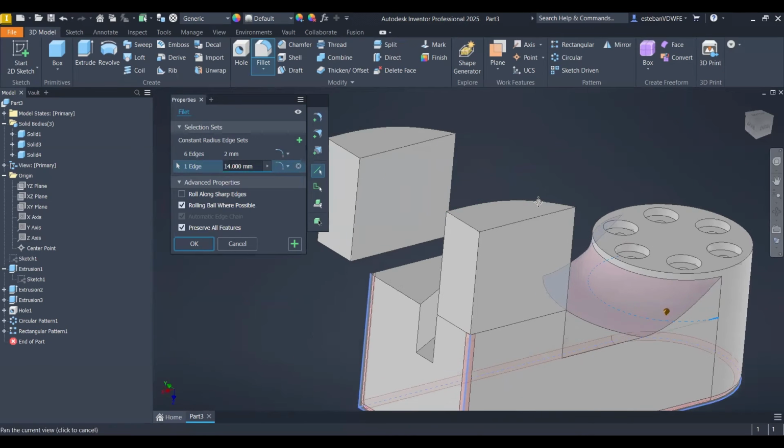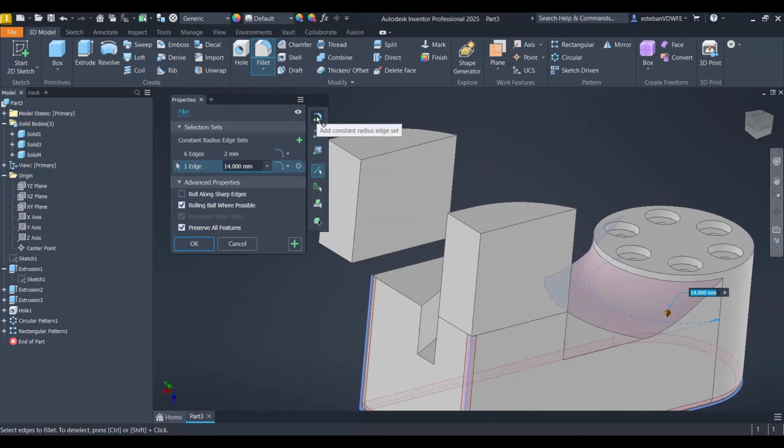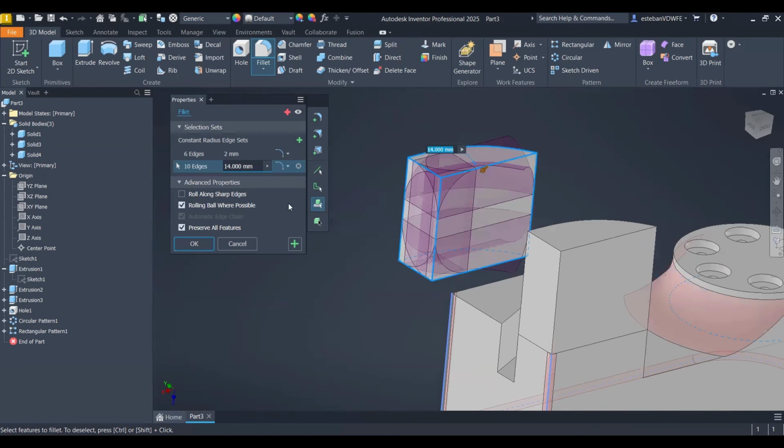You can also make it by not going one by one. You can select filters, let's say. So in this case, for example, I'm selecting a different one. Oh, okay, let me remove this one. I'm just clicking on Control and clicking it, since it has the selection priority on features, so it was capable to remove all those at once.